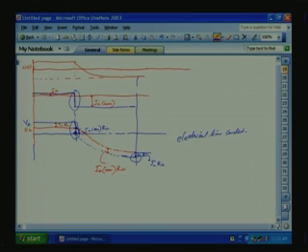Okay. So, if you do not properly control, what will happen? The machine can go like this, with large oscillations, and can settle after some time. Here also, if the control is not proper, this current can go like this, oscillations can happen. That will reflect here also, it can get into oscillation. So, instead of settling here, if the controller design is not proper, it will take a long time. So, we have to design the controller like that. So, how to design the controller?